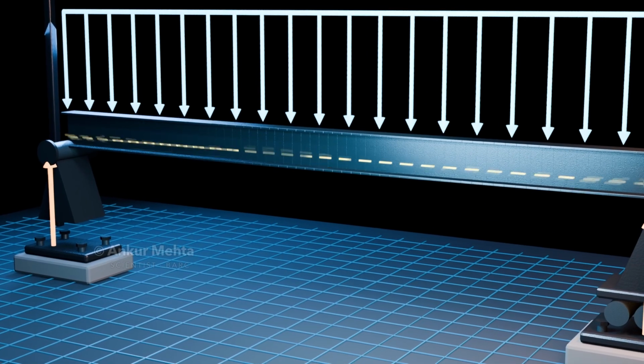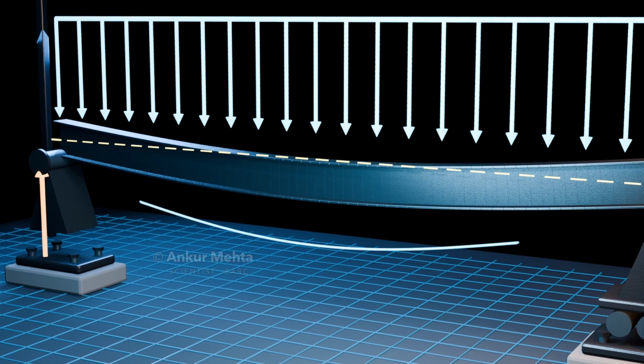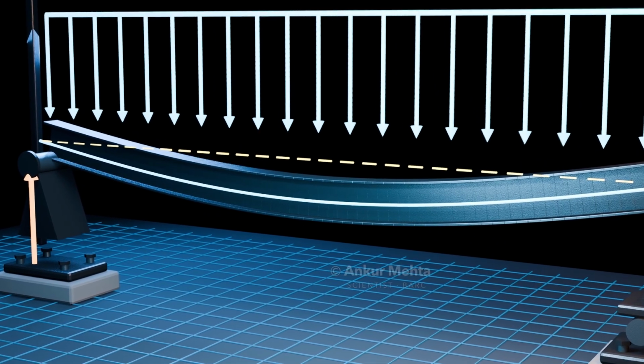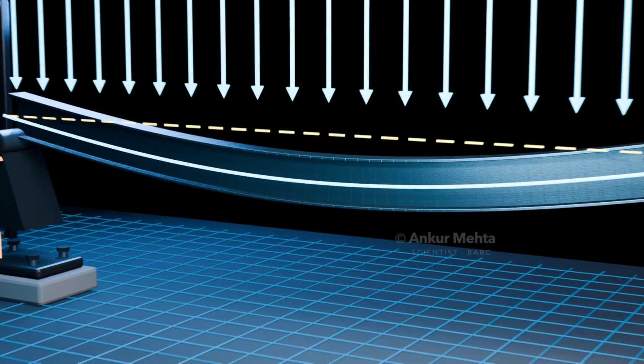As the load builds, the beam bends downward in sagging. The supports do not translate vertically, so the deflected curve returns to zero at both ends. The slope is largest near the supports, while the maximum vertical deflection occurs at midspan.